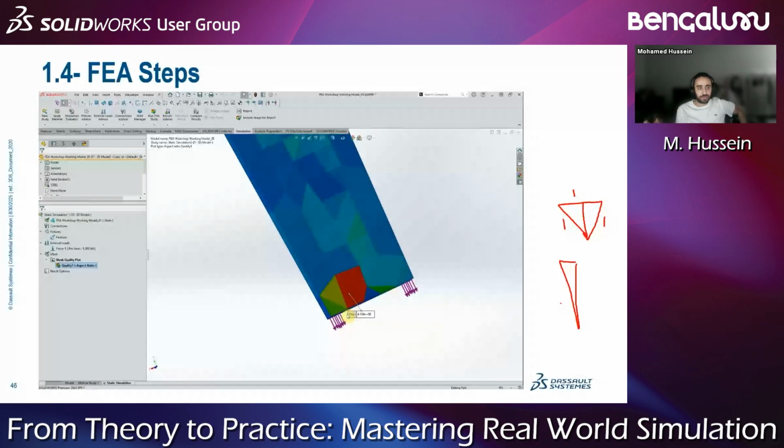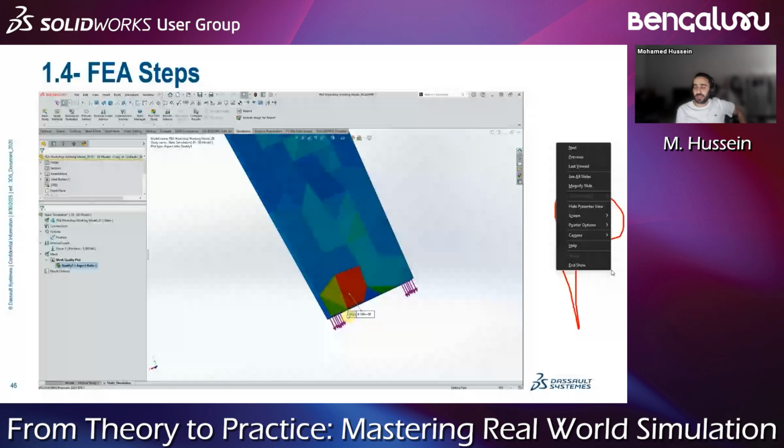So we are trying to have a mesh aspect ratio of around one. What may be accepted as the maximum is around 3 to 4, but don't use 10, 15 or whatever.